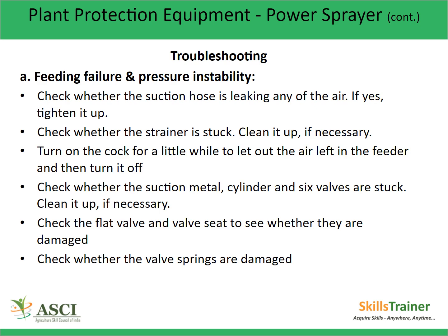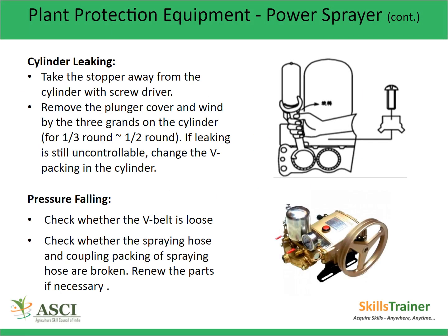Clean it up if necessary. Check the flat valve and valve seat to see whether they are damaged. Check whether the valve springs are damaged. Cylinder leaking. Take the stopper away from the cylinder with a screwdriver. Remove the plunger cover and wind the 3 glands on the cylinder by 1/3 round to 1/2 round. If leaking is still uncontrollable, change the V packing in the cylinder.